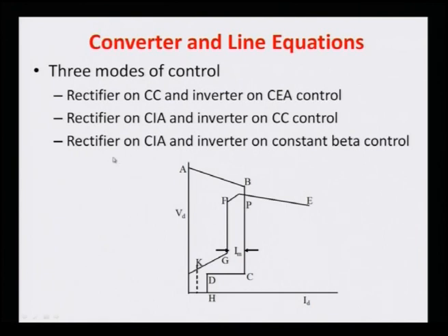There is also a possibility that we are operating here, and in this zone F, the characteristic given is called constant beta control, and I already explained why we go for all this control. This characteristic was completely defined, and I have taken it again from module 2, when the control characteristics were defined. So, we have the various modes of control, and we have to incorporate this.